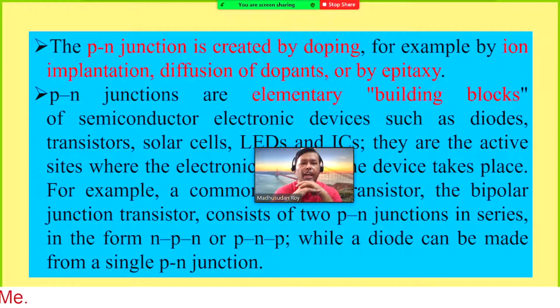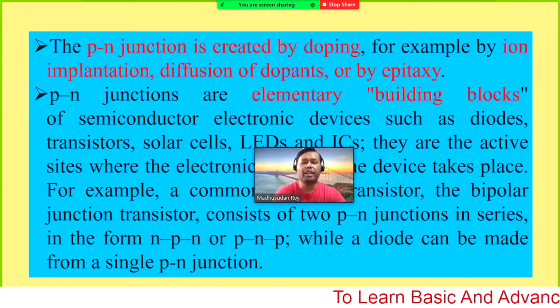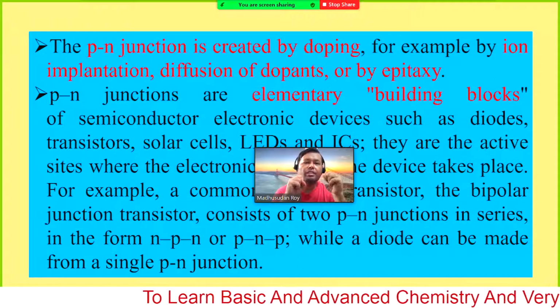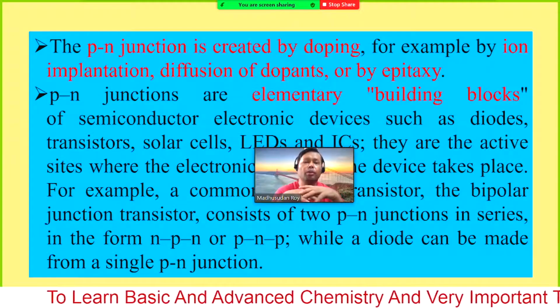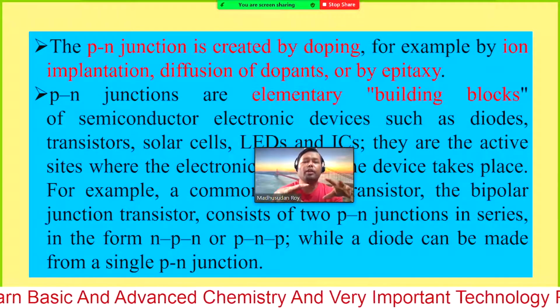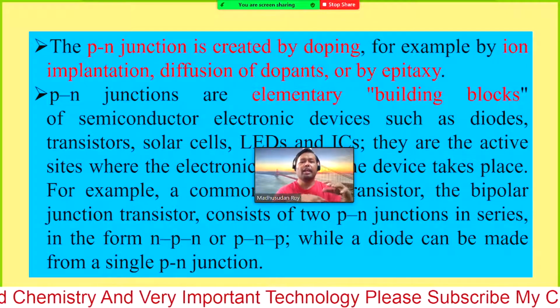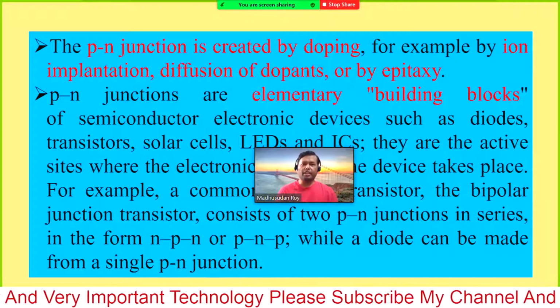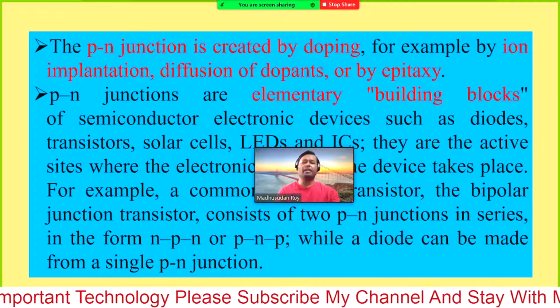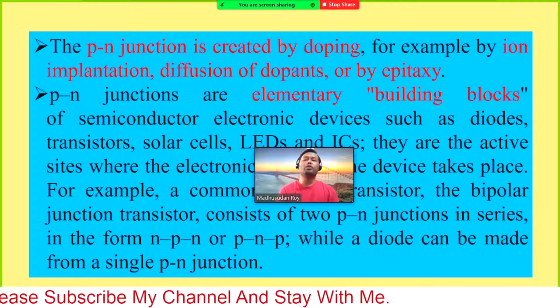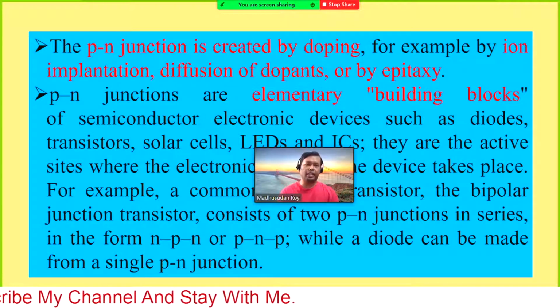Or by epitaxy. Epitaxy is a natural growth mechanism, a crystal growth mechanism. So you can prepare some crystal in a natural way. That means you have some liquid or some mixture of solution, and naturally you can keep it to settle down and then generate crystal over some time, but that is very difficult and you cannot control the size and shape of the crystal that way.